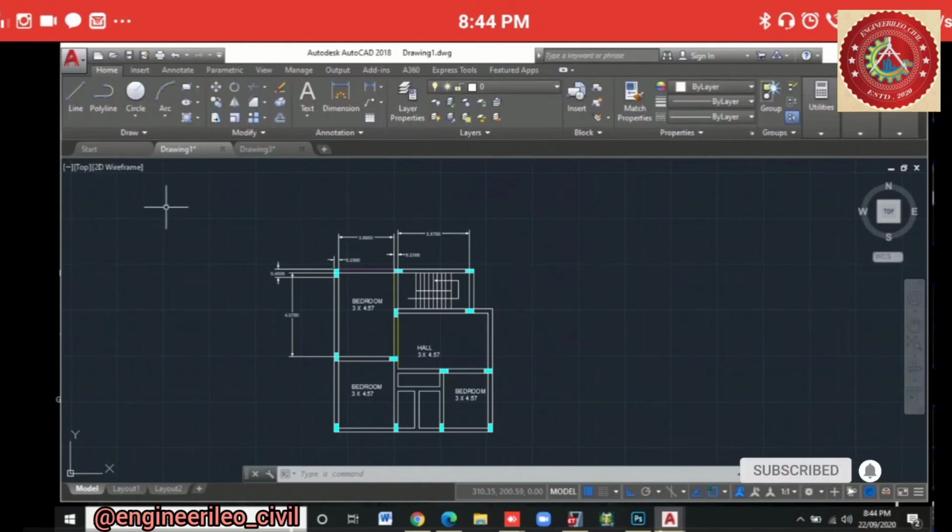So let us revise what we had learned today. First, how to create a line, how to edit it, how to trim it, how to extend it, how to mirror it, how to draw a circle, how to draw a rectangle and ellipse, how to hatch it, how to fill color in it, how to fill the color in the lines, how to do various things like the move command, how to rotate it, how to mirror it, how to fillet it, chamfer it, and how to offset anything, how to make stairs in a building.